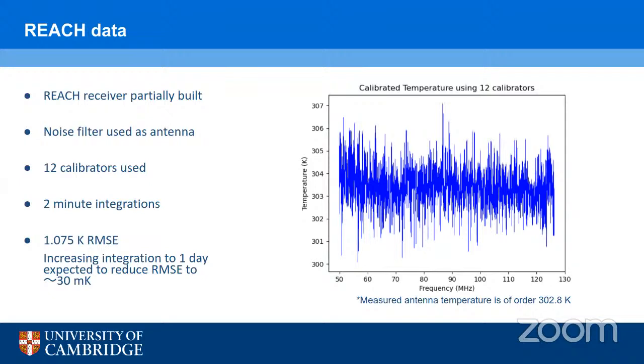As of right now, we are measuring our S11 to, I think, within 5 dB. So with our anticipated calibration accuracy, I believe we're meeting our S11 requirements. But once the receiver for REACH is built, we will have to explore exactly how accurate we need to make these S11 measurements. Thank you very much.